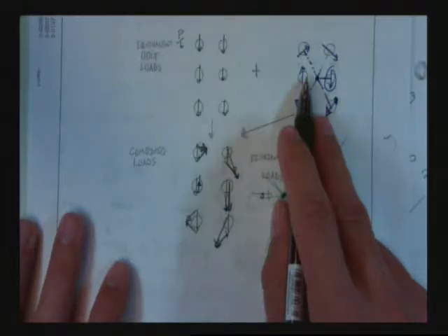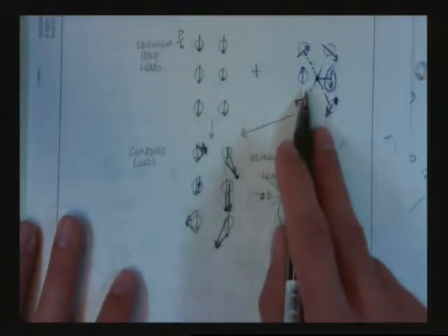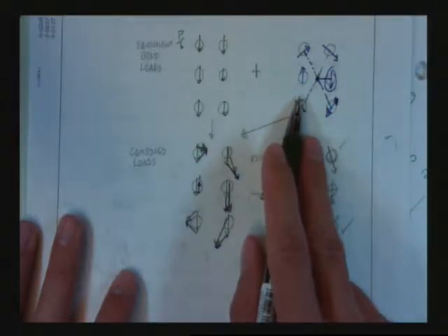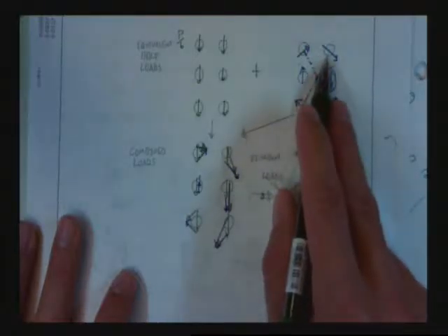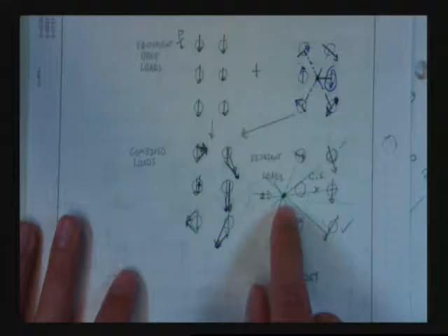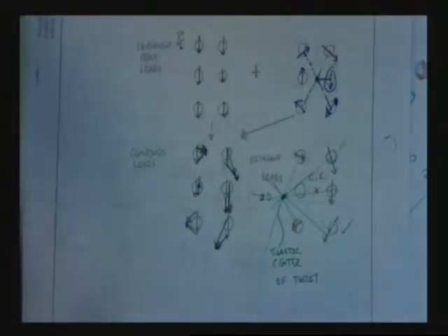If we're relying on elastic-based techniques, that breaks everything, because this can't happen anymore. So our center of twist may not actually be here. Let's say this bolt, the one we're relying on so much to be engaged, isn't. Well, then if that vector goes away, that's going to change where the center of twist is. You with me? So it doesn't actually ever happen that way. But it's a great make-believe story. Makes you feel good inside.